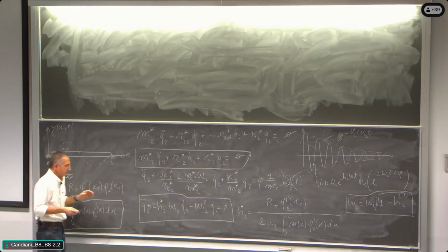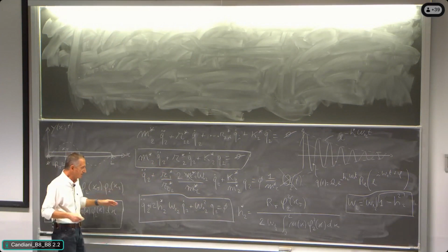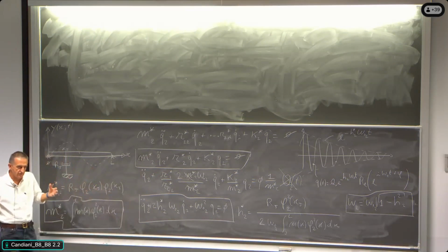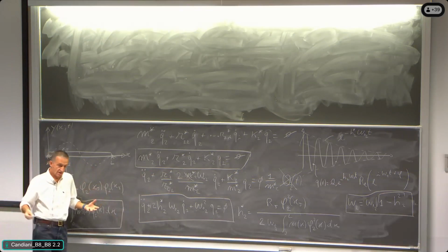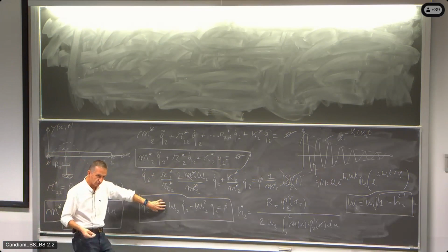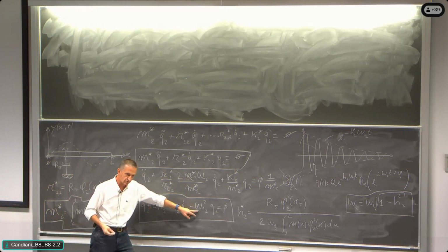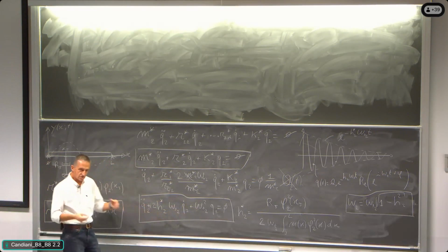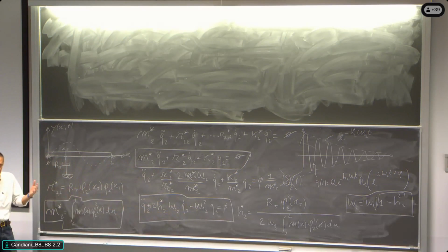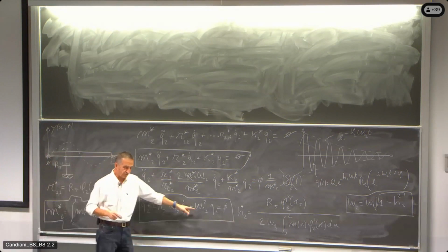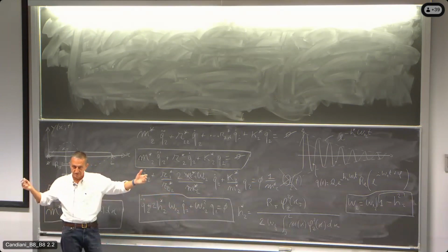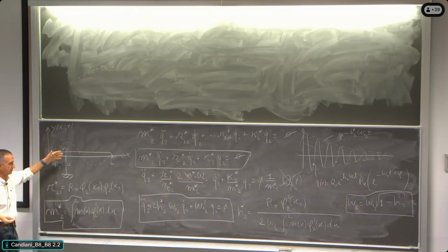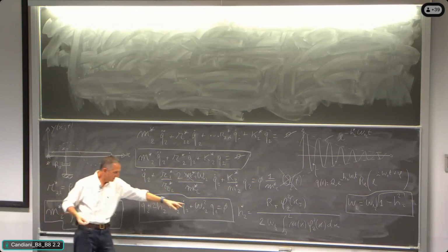Of course, the equation is always written in the same way. So we could have written this equation from the very beginning, because we know that the equation of the 1 degree of freedom system is written in this way. The only point is we have to give a number to this quantity and a number to this quantity. So we are working with the 1 degree of freedom system. The equations are always exactly the same equations. The only point is to put the right numbers into the equations, all right? And so this one is the natural frequency that is coming from the solution of the free motion of the problem. From the free motion of the problem, the second mode is giving this quantity here.